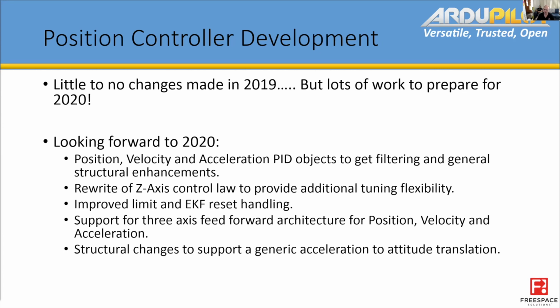We've improved EKF reset handling and limit handling in the attitude controller, and there's a few concepts there that we'd like to bring through as standard components of our control law design to handle those particular things. The EKF reset handling, for example, is we simply keep a record of our error, whereas that was just something we calculated on the way before.